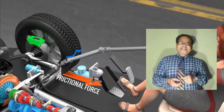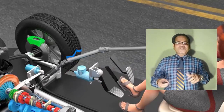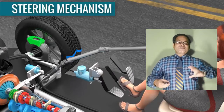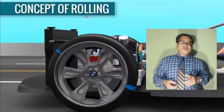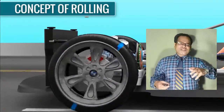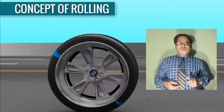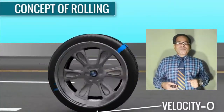To have a proper understanding of ABS, first we need to understand the principle of steering and braking. When we apply the brake, it prevents rotation of the wheel. And the steering mechanism works on the principle of rolling. The wheel always tries to avoid slipping on the road. The velocity of the wheel at the point of contact is always zero.